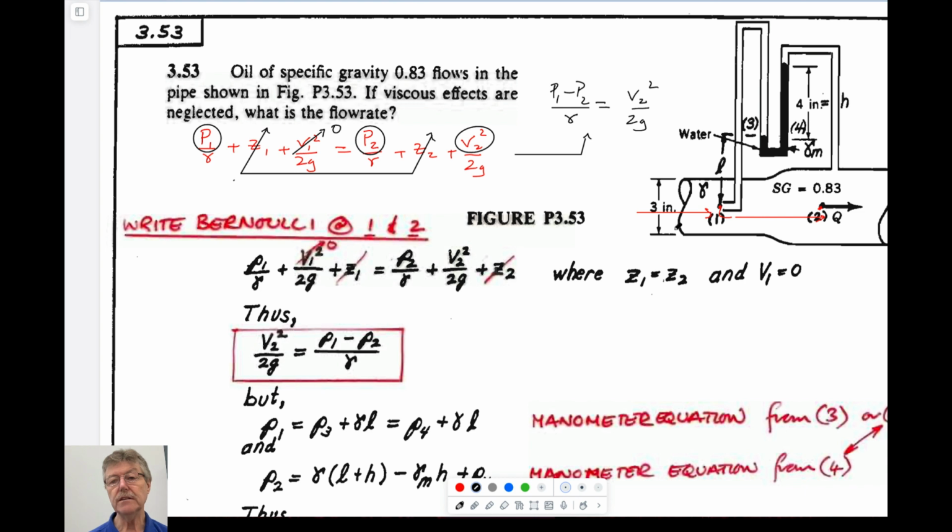And so our way to do that would be to assume that we know P1 and P2 and just go through the manometer equation. So I would write that, if you remember, P1. So we start off at P1. We go up some amount, which is L. If I get this right, you remember I got it wrong last time. Going up in a swimming pool, you reduce pressure, so you subtract.